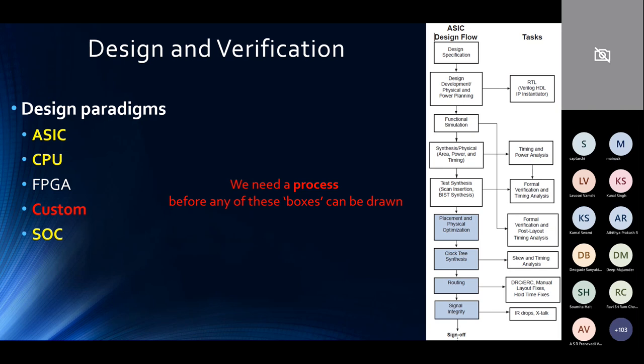The area scaling, the power and performance scaling that you generally achieve on all these process nodes, cache, SRAM, and all these embedded memories play a major role enabling that. And there are still designs where people actually hand draw structures to make sure your yield is correct. When you move from one process generation to the next, you are still able to yield at a very high level on your SRAM bit cell. Unless SRAM bit cell works on a given node, no matter how great your architecture is, you are not going to have any product at hand.